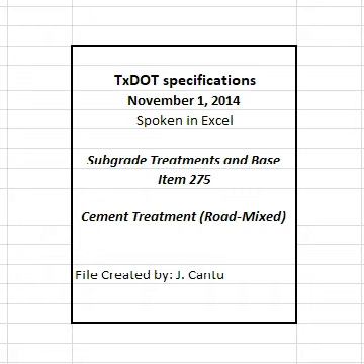4.8 Curing. Cure for at least 3 days by sprinkling in accordance with Item 204, Sprinkling, or by applying an asphalt material at the rate of 0.05 to 0.20 gallons per square yard, as shown on the plans or directed. When a section is microcracked, cure the section for an additional 2 days after microcracking. Maintain the moisture content during curing at no lower than 2 percentage points below optimum. Continue curing until placing another course.